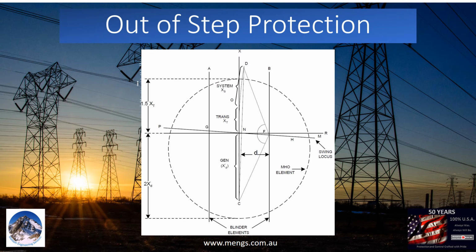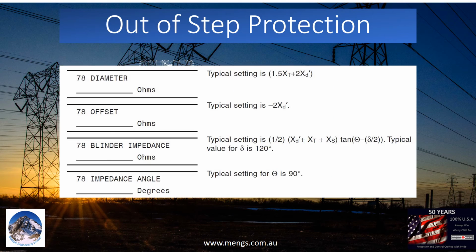To set the relay, we need to know the electrical center of the system. The generator's transient impedance, step-up transformer impedance, and system impedance are required to calculate the electrical center of the system. Here is a typical setting.